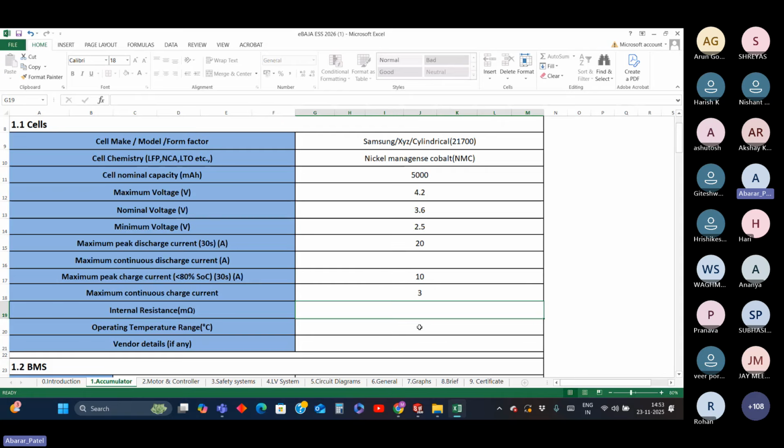And using Ohm's law, V equals IR, you can then calculate the DCIR of your cell. In whatever conditions, the lower the resistance of your cell, the better the cell. Internal resistance mainly depends on various variables, such as how old your cell is, or at what temperature you are measuring. So this is a dependent characteristic of an individual cell.